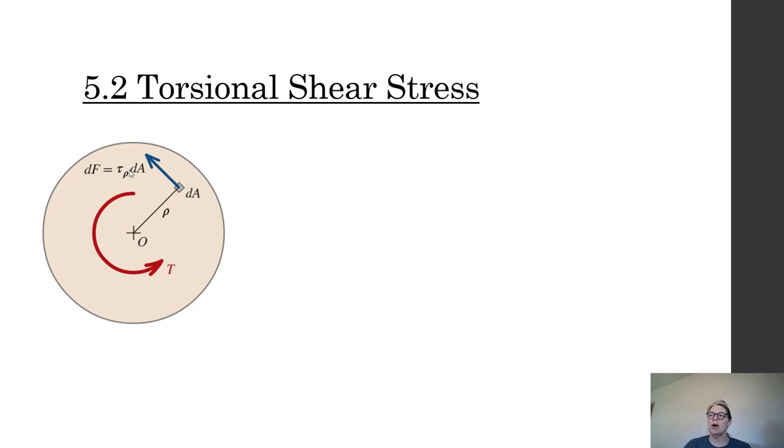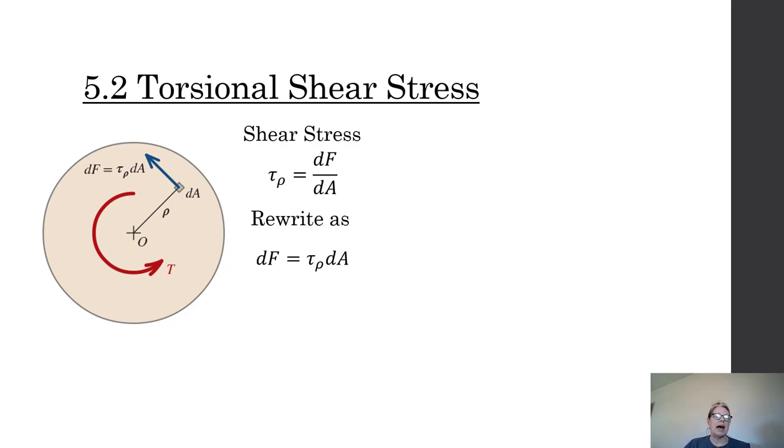So if we take that cross section and we're looking at that applied torque, well, what is torque? Torque is a moment, which is force times distance. So if I look at a little differential element that's some radial length away, I know then that shear stress has to be a function of that force and that little tiny area that we have. And I'm going to rewrite this as dF equals shear stress dA.